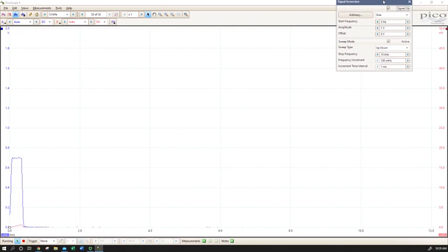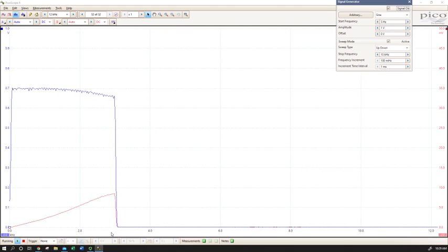Because we've gone to a larger frequency X scale, all of those small window peaks that we were plotting when we were only displaying full scale of 2, now they're all stuck together. And we're only taking the very high points. So this line is actually the peaks of a whole bunch of those little Gaussian displays that we saw when we only had a full scale of 2 kilohertz. That's pretty typical as we're collecting in frequency mode.